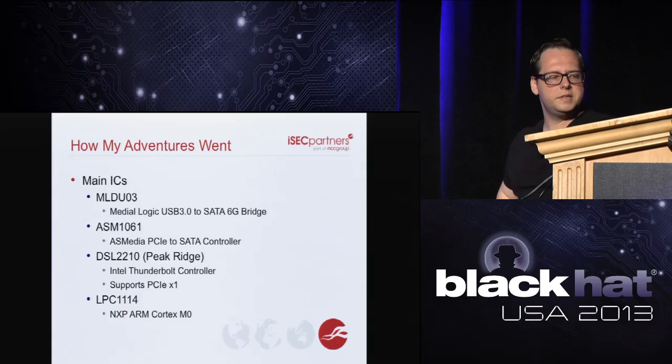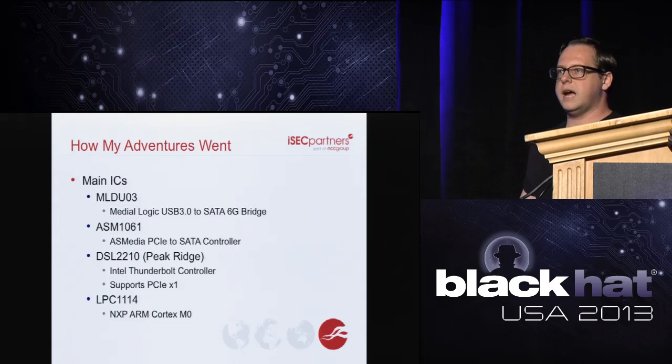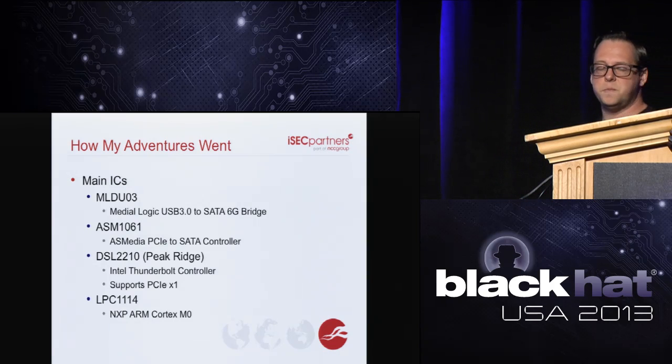And then we have an LPC 1114. It's an ARM Cortex processor. Not really quite sure what this is doing here. AnandTech thinks that it's to switch between USB 3 and SATA, but we've already identified those paths and how they interact. So that's basically just setting wires high and voltages. So we really don't think that that's the solution, but we're not quite sure what that is yet. So we need to keep digging deeper.